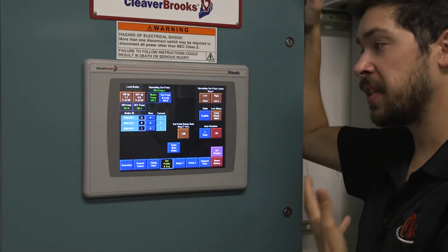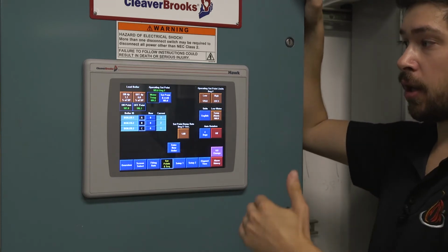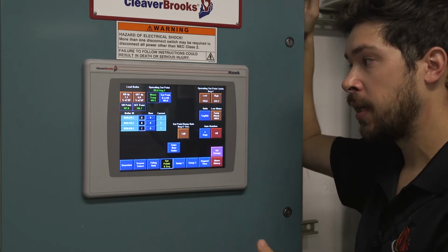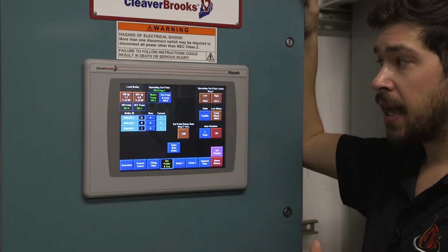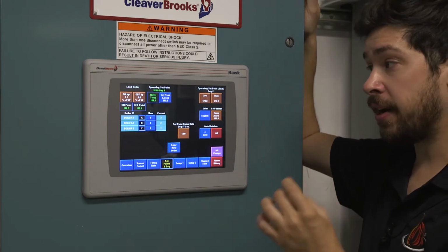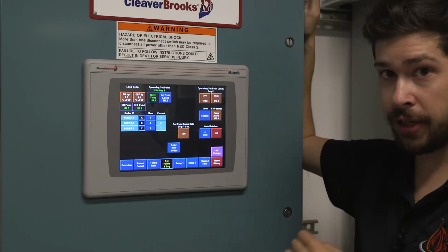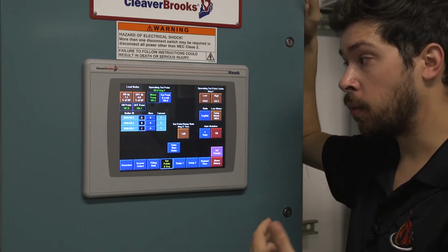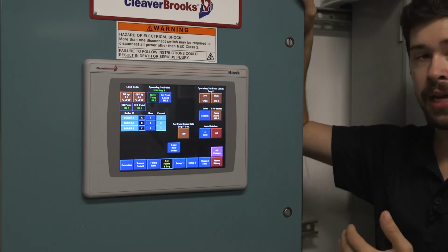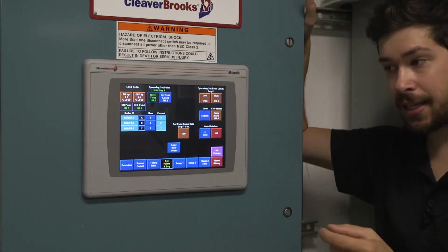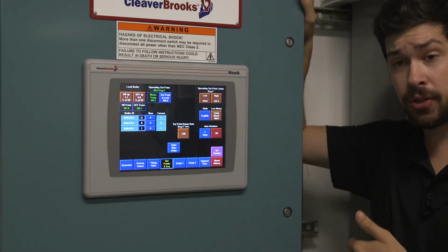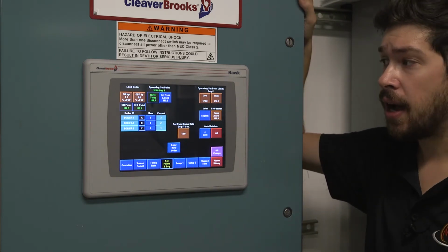So essentially what we're saying here is, the number that I want you to keep, ideally in a perfect world, is 185. And the boilers, if they have the right load, will fire and maintain almost exactly 185. We almost never work in a perfect world. There's fluctuations in the load. Sometimes it's too low, times like these, in shoulder season, where it's 80 degrees outside.